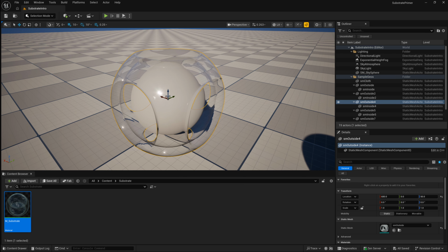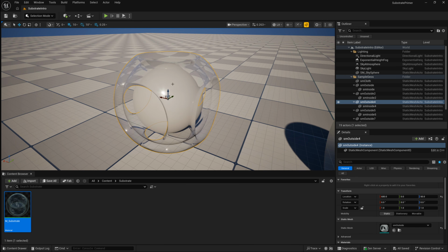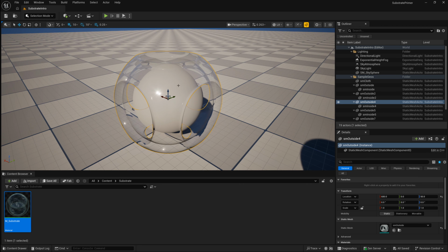Even though it's totally not, it feels better than what it was before with just having that IOR value. So this is something you can do to cheat it. You can blend between a different IOR from the facing angle to grazing angle to still get a bit of distortion in your glass, but not have it totally break when you have something inside it like this.